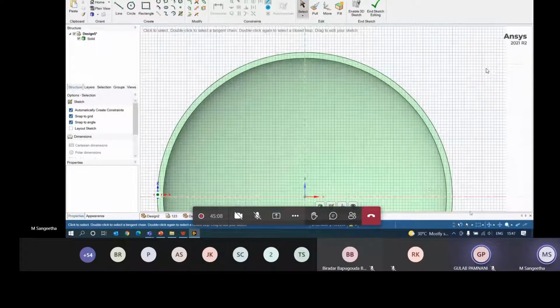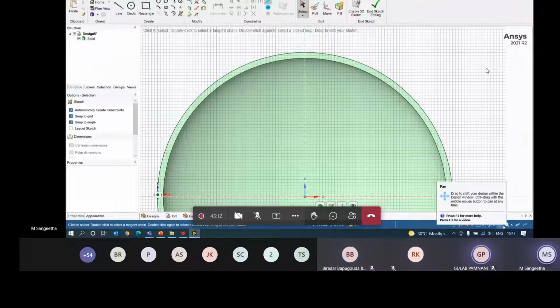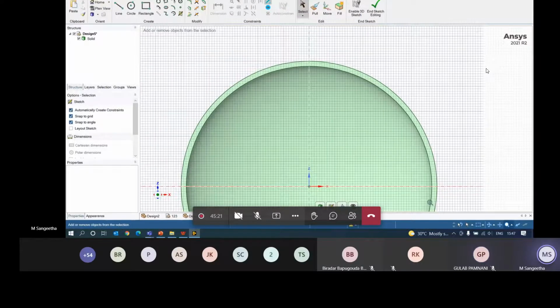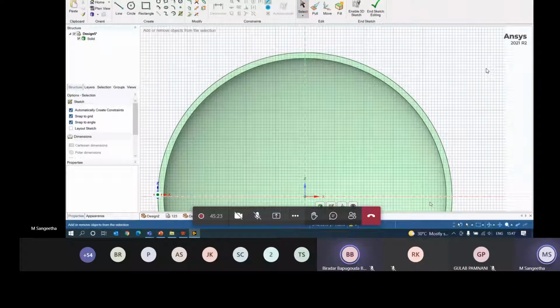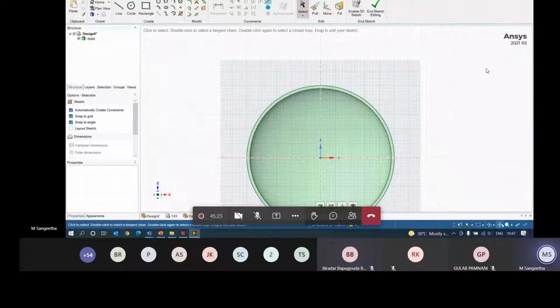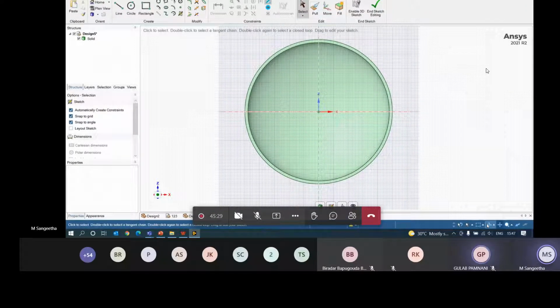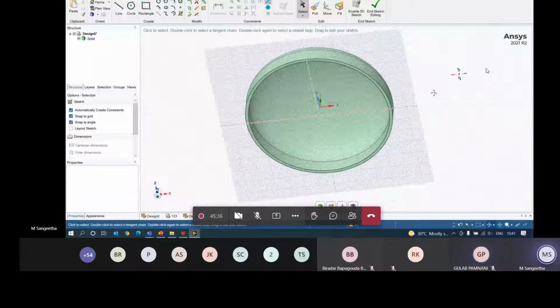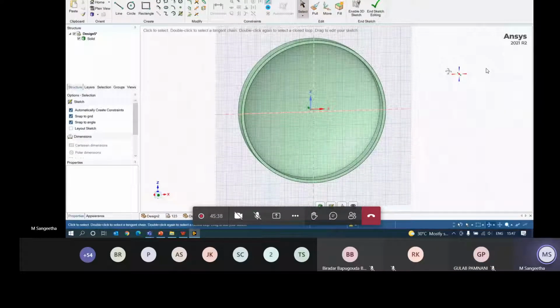And here also you have options like, to zoom from here, it's always difficult to zoom, taking all the time zoom and then doing, rather you can go for control minus and control plus. Okay, and if you want to pan your geometry, make use of pan tool from here. And to spin, you can directly spin, you can enable this one, or you have your middle mouse button to spin it.